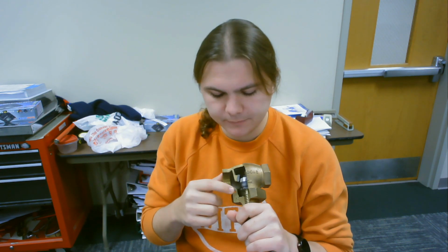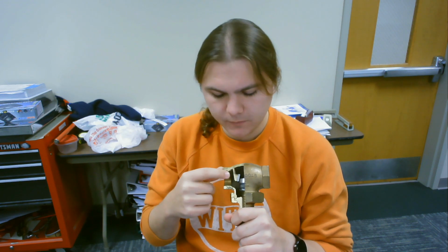When it does that, as you can see this cutaway area, when you have that on your drawing, you're going to hatch all the cut area, and then the rest of it is just going to be empty space in your visible lines. There are no hidden lines more often than not when you do a section view. So I'm going to show you how to do that in Solidworks and AutoCAD.